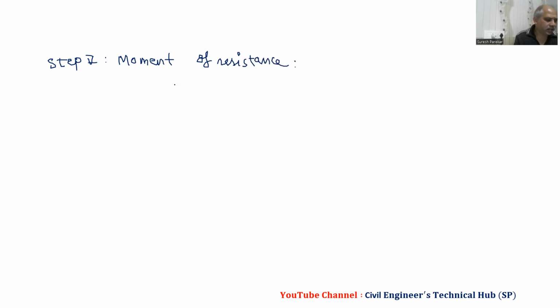And then we have this MD because we have to calculate MD also. So MD is equal to beta B ZP Fy upon gamma M. Actually, this is step 6. We have to go for step 5, shear capacity.